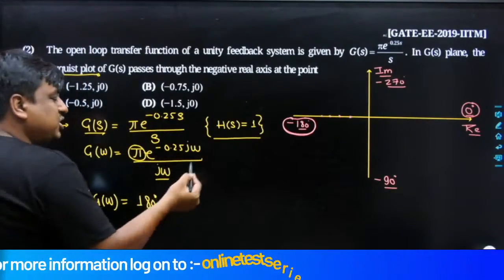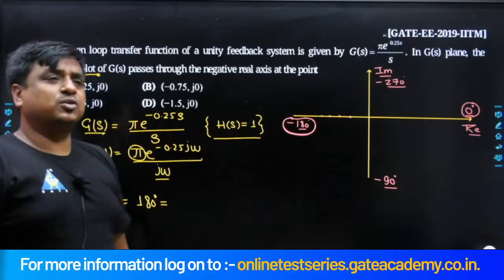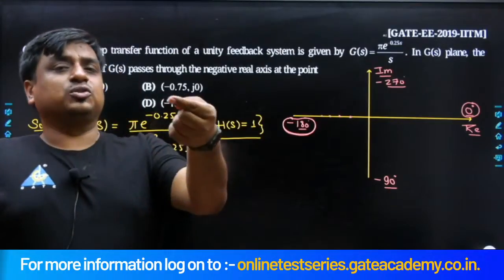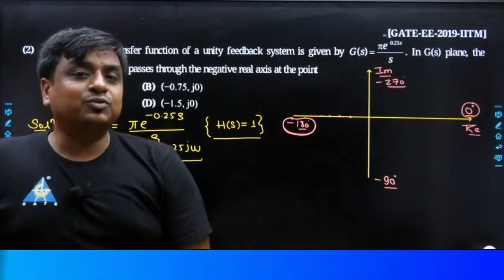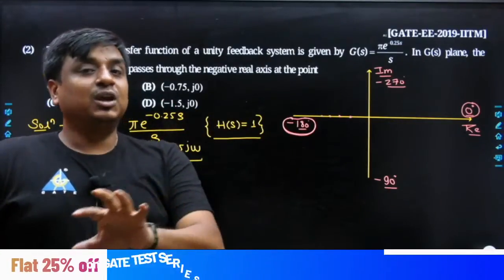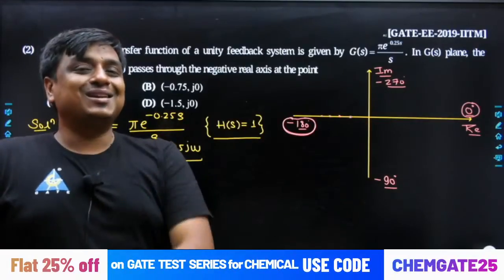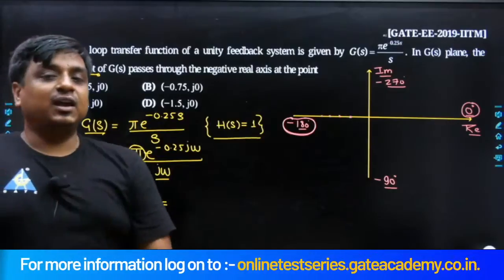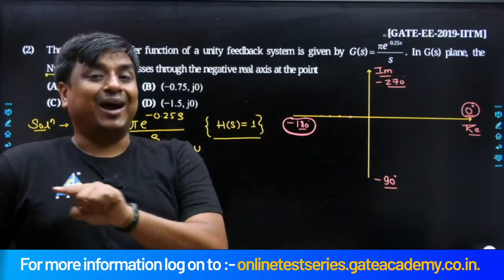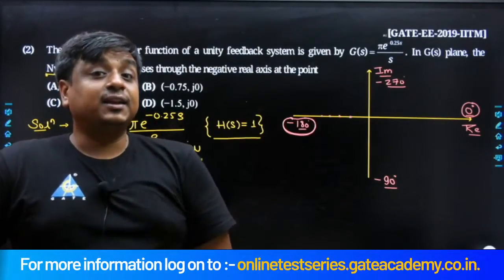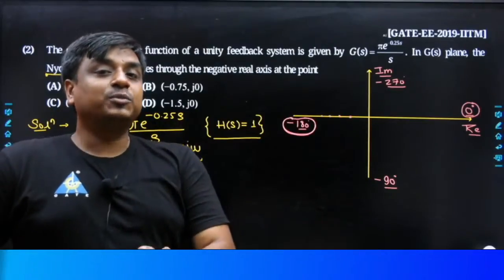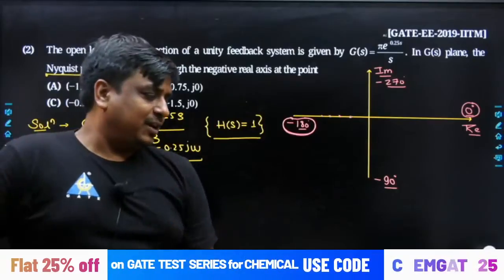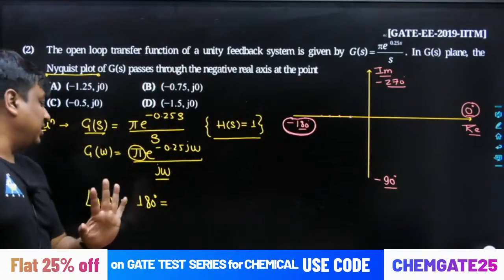Because of jω we have already seen earlier, because of 1/s we would have the introduction of a phase of minus 90, because of 1/s² minus 180 degrees, because of 1/s³ minus 270 degrees. In general, 1/s raised to the power of n gives an angle of minus n times 90 degrees, and that remains independent of the operating frequency ω, whether ω is towards the lower side or the very higher side. Could you really understand what I am saying?